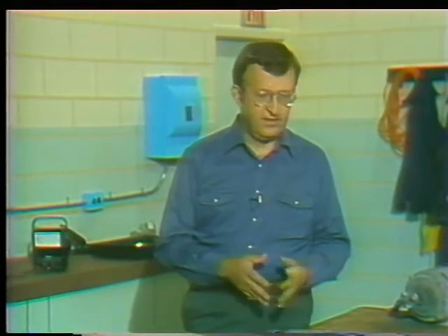Okay, say you test the stator for grounds. There aren't any. Then you test for opens, no opens. Well, the problem is most likely a short. A short is an accidental current path of low resistance. When a short occurs, a conducting path interferes with one of the normal current paths. The current takes the path of least resistance through this new course.